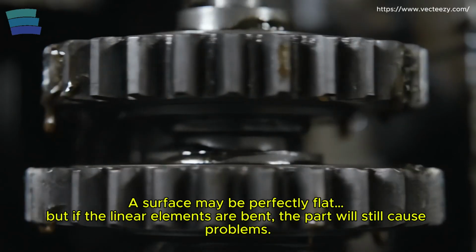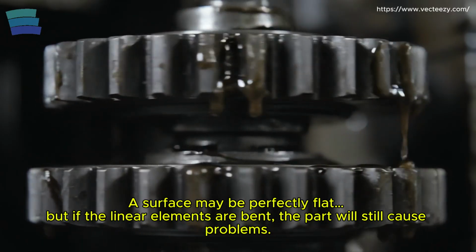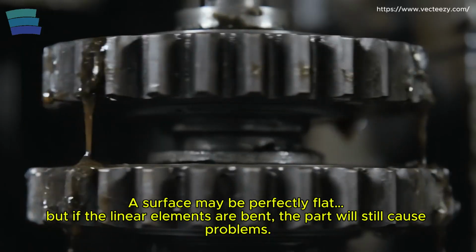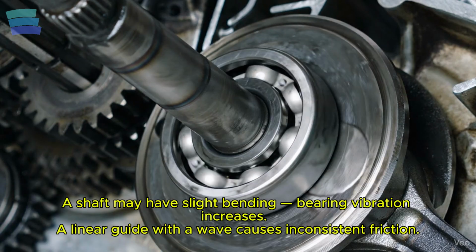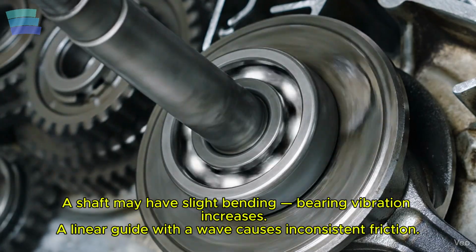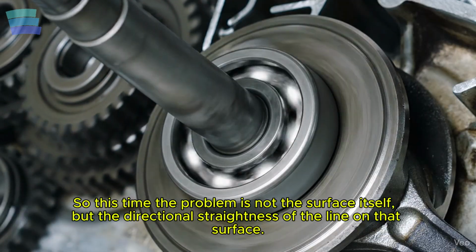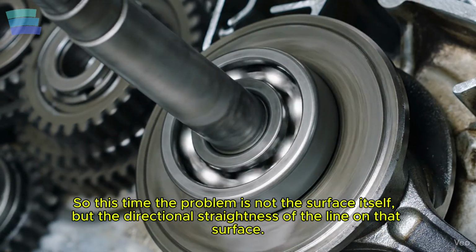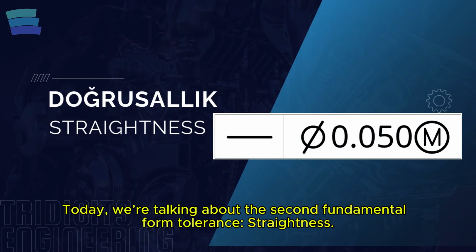A surface may be perfectly flat, but if the linear elements running across that surface are bent, the part will still cause problems. A shaft may have slight bending, bearing vibration increases. A linear guide may have a wave along its length, friction becomes inconsistent. So this time, the problem is not the surface itself, but the directional straightness of the line on that surface. Today, we're talking about the second fundamental form tolerance, straightness.